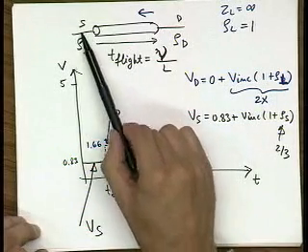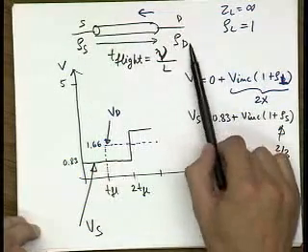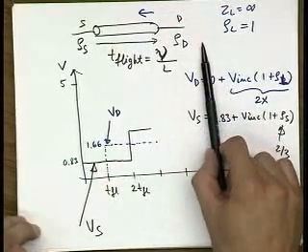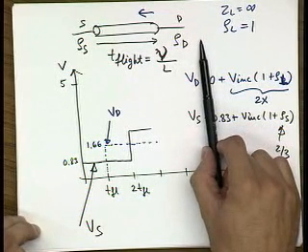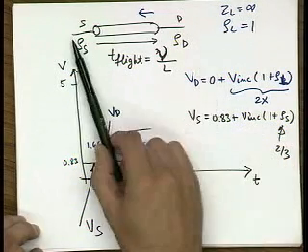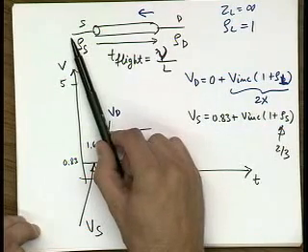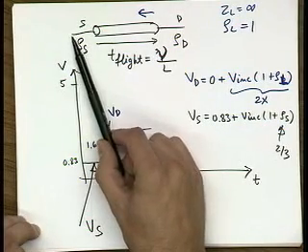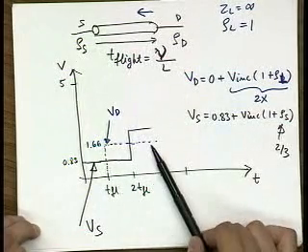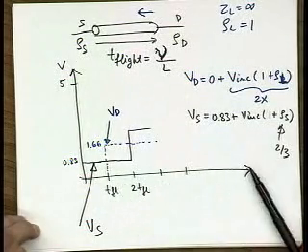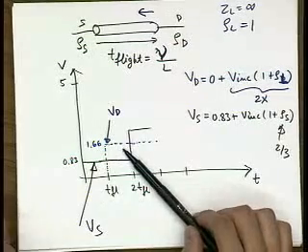For that you define reflection coefficients based on termination resistance, or termination impedance rather, at the destination side, and you also have the driver source resistance at the source side. Then you basically apply this formula and roll over in time to figure out these waveforms.